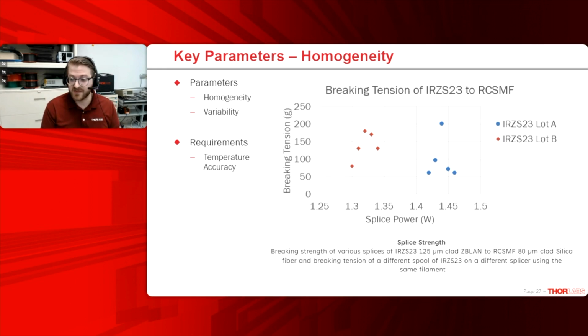And the only difference there is just it was a different lot. I used the same glass processing system with the same type of filament. I even balanced both systems to have a similar heating effect, both in the melt back of the ball as well as the diameter of the ball on both sides. So there is just difference in one lot to another on what strength you can expect.